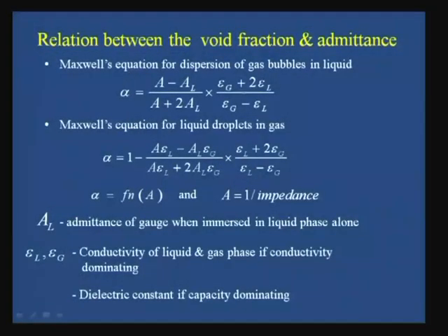When we are dealing with dispersed systems, then we can use the Maxwell's equation. If you see the Maxwell's relation, it expresses alpha in terms of the admittance of the two phase mixture, the admittance when the tube is full of liquid, and the dielectric constants or the conductivities when the tube is full of water and when it is completely empty or full of gas. Now, when it is a dispersion of gas bubbles in liquid, this is the relationship. When it is liquid droplets in gas, this is the relationship.